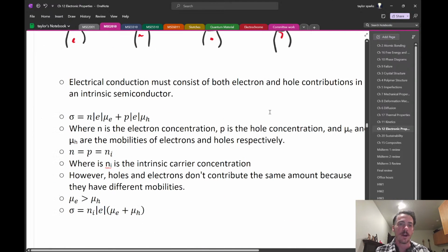Both of those can contribute to the overall electrical conductivity, so we account for both of them. So if you look at the equation that arises from this, here it is, it's got both terms. The overall electrical conductivity is equal to the first term, which accounts for the number of electrons, N, your electron concentration, the number of electrons per volume typically, times their charge, the absolute value of the fundamental charge, times their mobility, the degree to which they are able to easily move, right? That's essentially the electron friction that we sort of alluded to. And then you have the second term, which accounts for the number of holes, right? So you have the concentration of holes times their charge times their mobility. You have to add those two together because, even though the mobilities might be a little different, they're both going to be important.